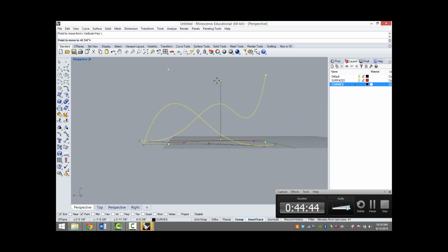So when I specify moving in the vertical direction, which is actually quite useful because Rhino sometimes can't interpret which way is up, I type move in the command line and then V for vertical. And then I'm just moving in this direction. And if I want to specify the distance that I'm moving to, I can just type in, let's say, 20 feet. Okay? And then enter. And escape to turn the points off.